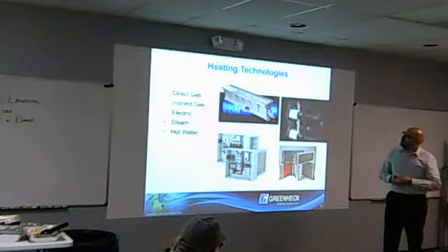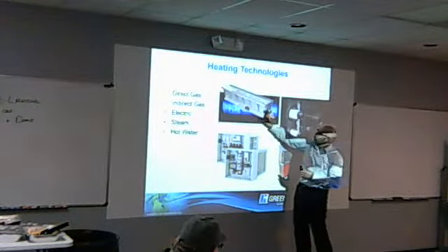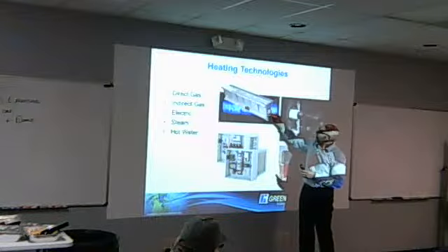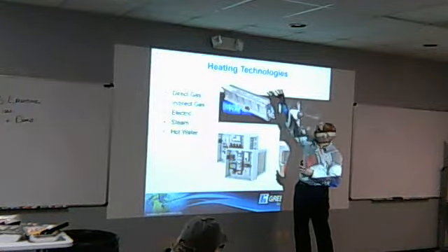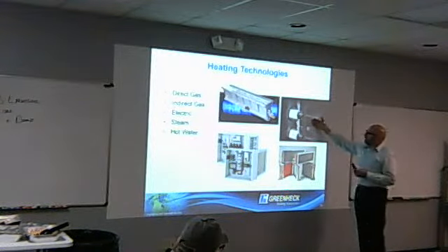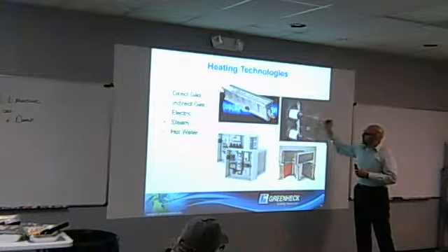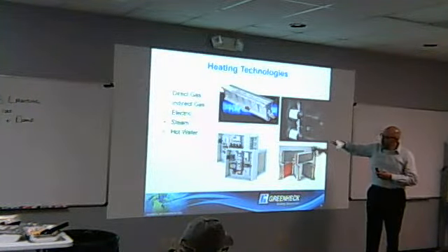In terms of heating technologies, direct gas, indirect gas. Direct gas, that flame is going to be right in the airstream. This is a flame picture of a manifold. The gas comes in, fires, comes off the baffles and then is drawn into the air. Indirect fire, you're familiar with that, heat exchanger firing down a series of tubes, could be a serpentine tube or